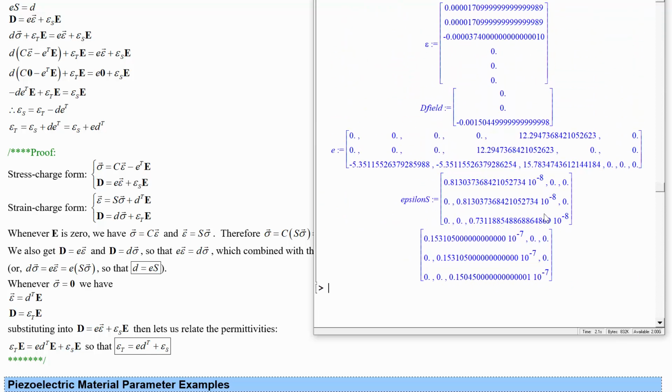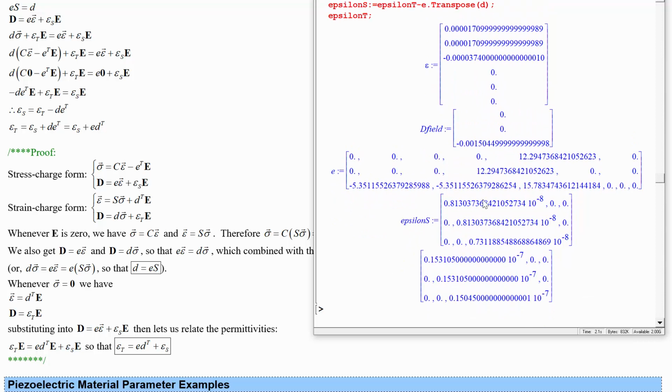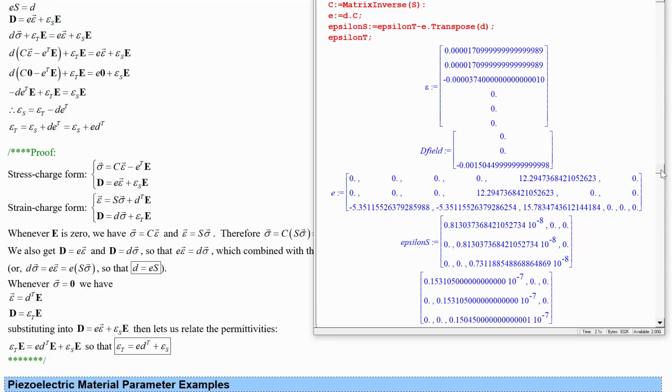Being, in the case of this PZT5A, possessing components that are about half as big as epsilon t was. So it's not so obvious how this is all going to work out, right? How is it that we are going to have strains in X and Y for this original material, yet when we take E and multiply by the non-zero strain rather than multiply D by the zero stress vector, we're still going to have zeros in the X and Y components?